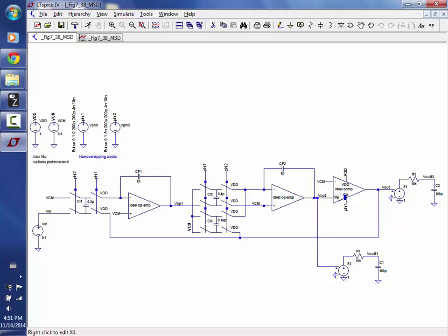Yeah, you're trying to characterize the gain of the comparator so you can select these capacitors to maximize the swing, because ideally you want this swing to be as big as possible, because then you have large forward loop gain, right? And then you can resolve smaller signals, right? Yeah, trying to figure out how to select those but let me ask this.